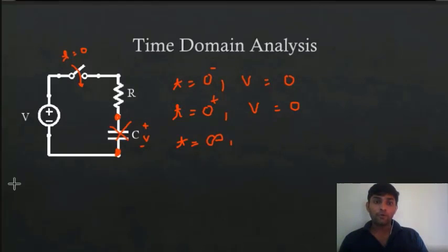Yes, because you told me the answer like V minus IR. Now because this capacitor is open circuited, the voltage across it will become V only, because there is no drop across this R. The voltage drop across R will become 0. So the total voltage across this capacitor will be V at steady state, because that's the condition of the charging of the capacitor. This is just a property of charging of a capacitor.